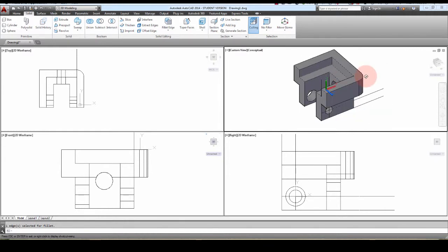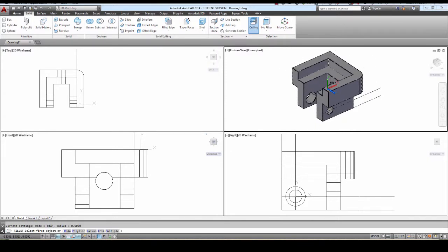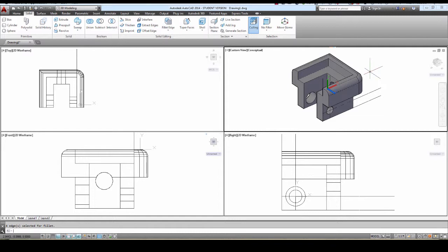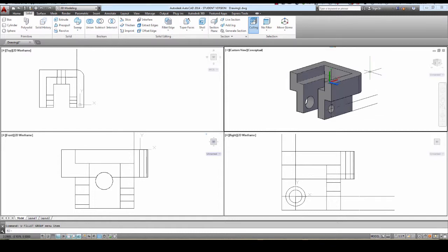So if I wanted to fillet an edge all the way around the top of this, then I could use fillet and pick this edge right here, and I'll say 0.25 this time, and I'll say I want it to be a chain. So I'll pick my second part right here, and it comes across like that and to there. And if it was a loop, then it would have picked the whole entire loop, but I can do a chain like that, and it will just round those edges over like that.